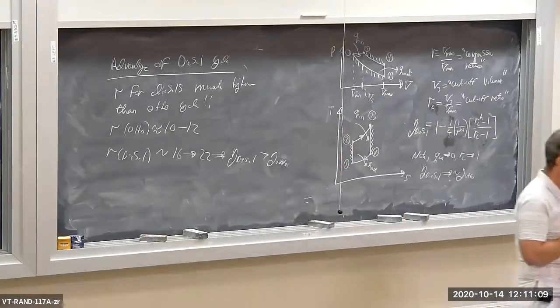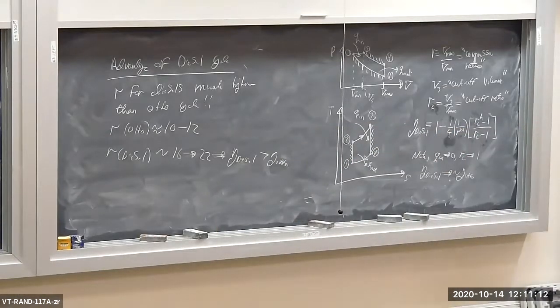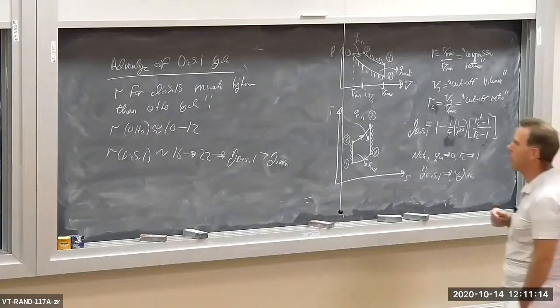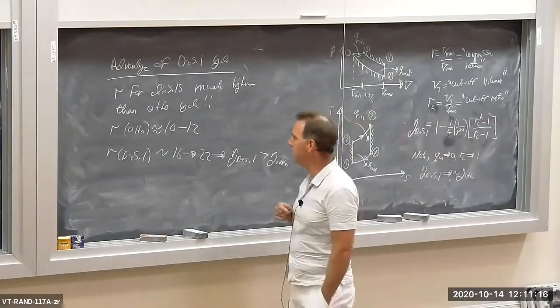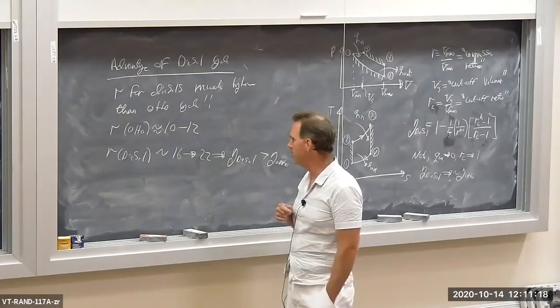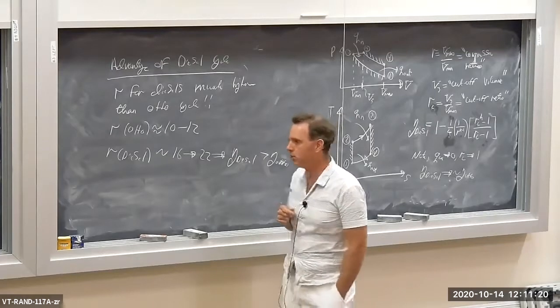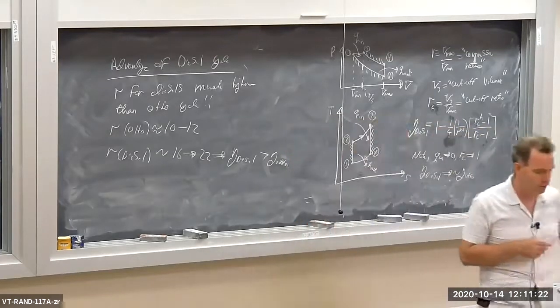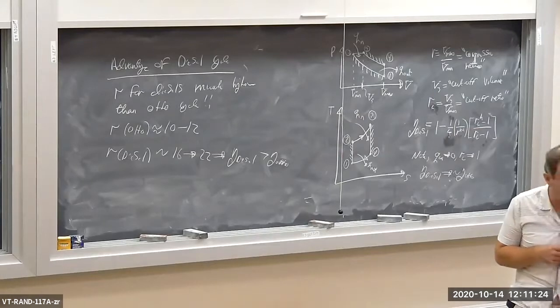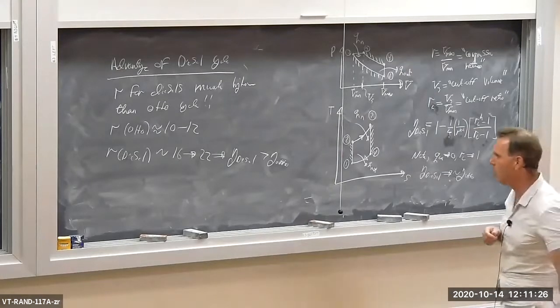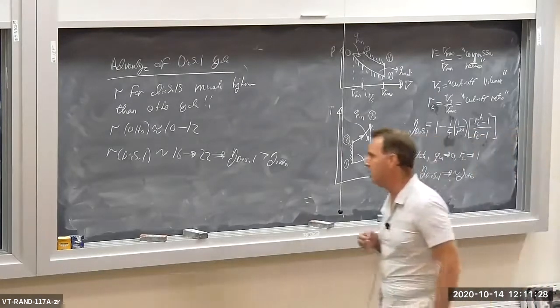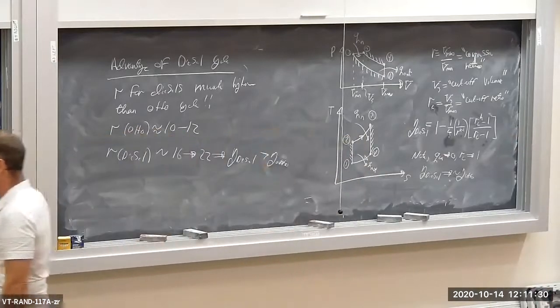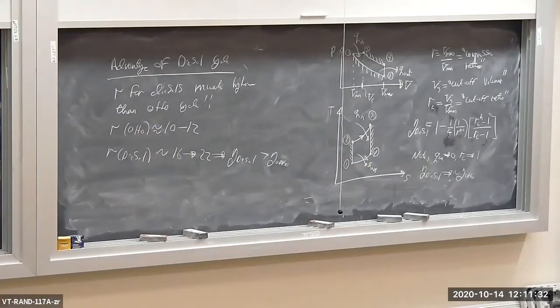Gasoline engines are typically now going towards the diesel cycle, even though they use gasoline, and they're able to do that because they can inject. They're developing high pressure pumps and high pressure systems for injecting gasoline. So gasoline engines are actually going more towards the diesel cycle with the use of high pressure direct injection for gasoline engines now as well, okay?